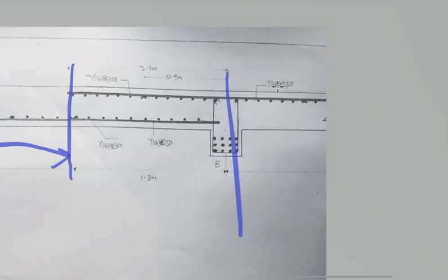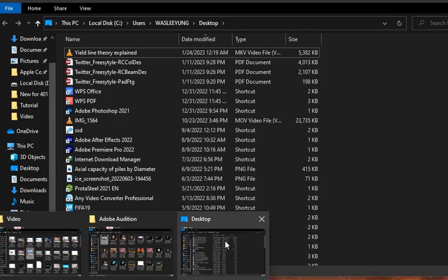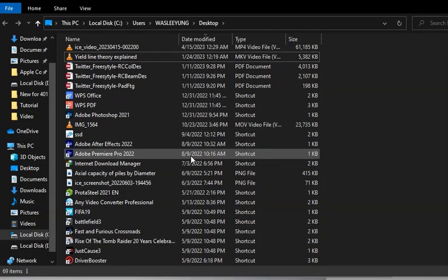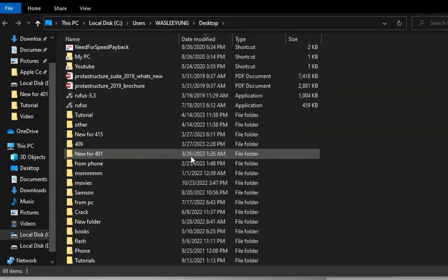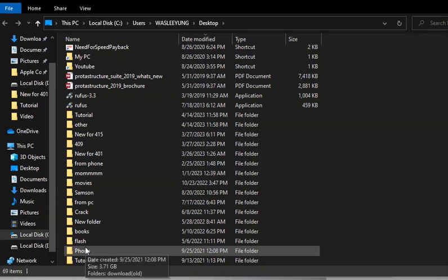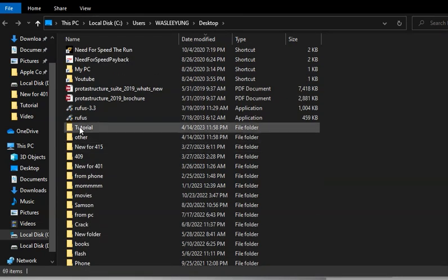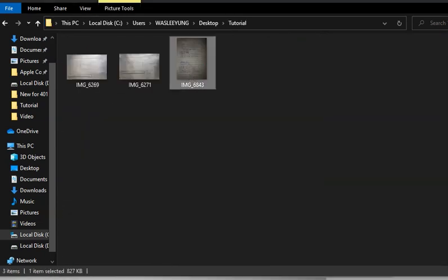So for cantilevers, we have our bending moment, which is always negative. That means our reinforcement will be at the top. That is why we have it at the top here. Our main reinforcement is at the top, while the distribution reinforcement is at the bottom, which are the dots that you can see here. So now we are going to take the whole of our area, our complete area, at the center span, then half of it also, just as we did on the other parts.